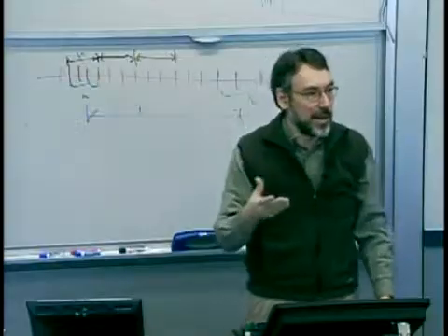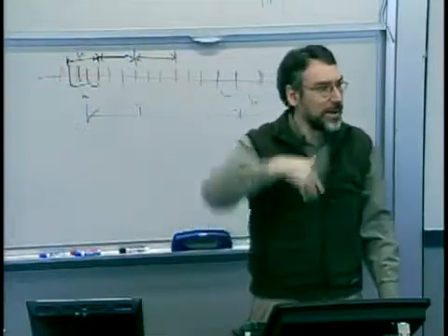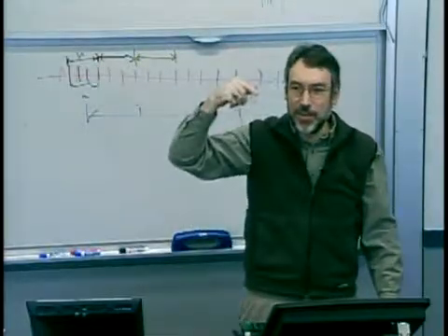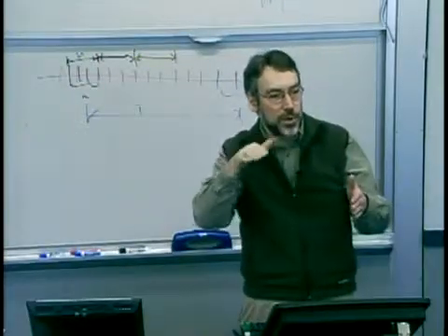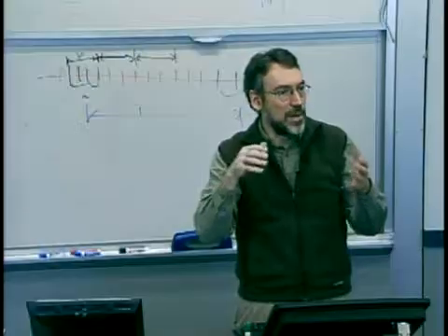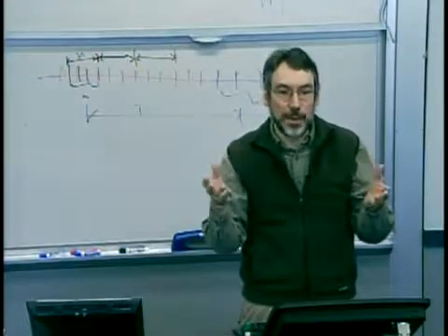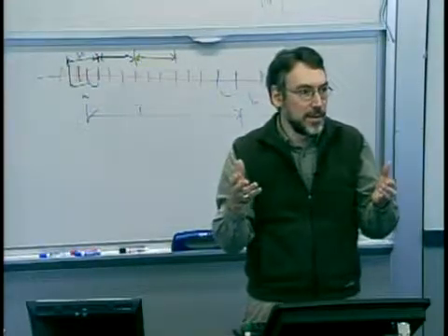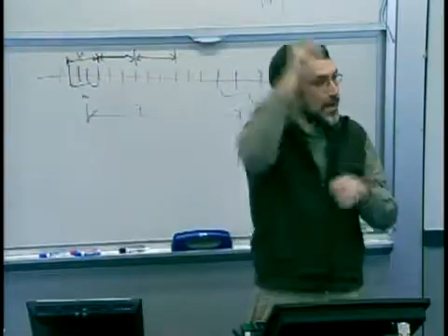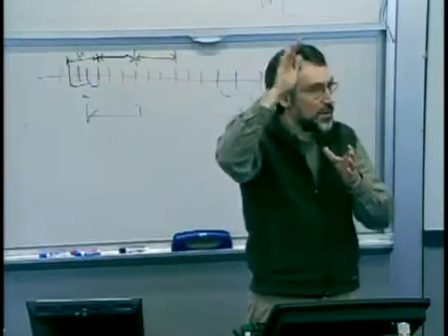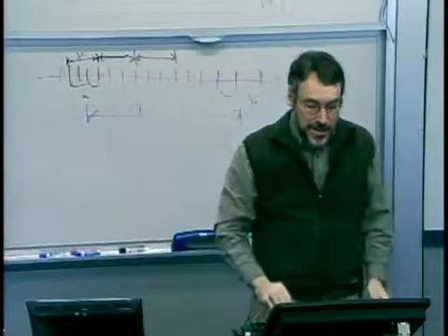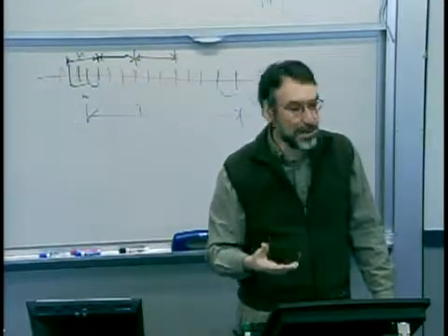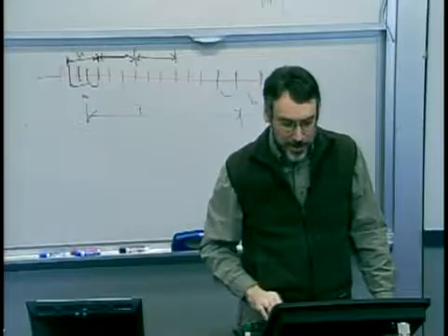Another way of looking at it is we're filtering high-frequency deviations down to try to detect a smoother average that's more indicative of the true mean of the process. I'm really not trying to detect variances. I'd just as soon have one signal that just told me how good my mean is. And so an X bar really does filtering of your data.